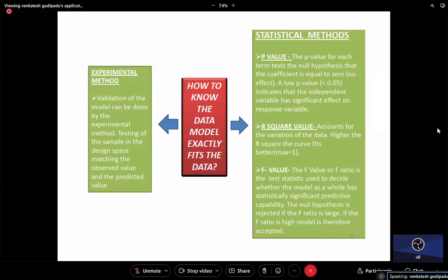Just for a simple understanding, if you buy a simple thermometer, then they will give you the calibration value, and you need to reach that particular value, right? Then only is your instrument working. Otherwise, you can assume that your instrument has some error. And what is that error? You need to find out, and you need to add that error if you want to reuse that instrument. Otherwise, you need to go for another instrument. So there are various methods to validate.